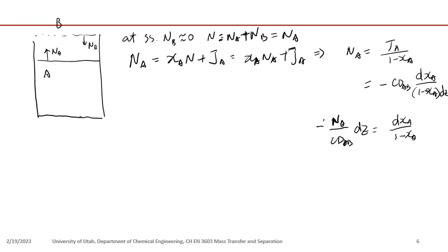And we have a ground contamination problem, which is basically a semi-infinite diffusion problem where you have a reservoir of concentration A here. Then this species A is diffusing into this semi-infinite space. This is Z equals 0. The initial condition is that CA of Z is 0 in this region: when Z is larger than 0, your initial concentration is 0. Then there are two boundary conditions. One is on the left, where you have a fixed concentration. On the right, at infinity, you have 0 concentration. And you can solve for it.